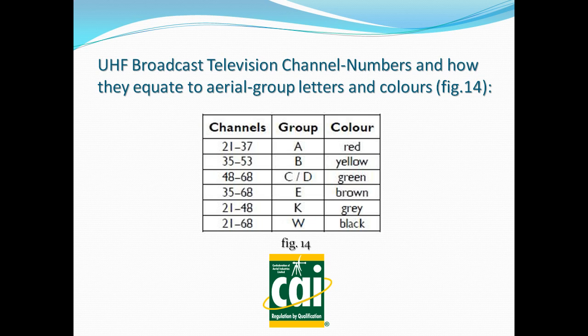In some parts of the country, UHF channels are allocated to transmitters which are spread across both UHF band 4 and 5, and widely for one or two transmitters. That's because of frequency planning measures due to interference from transmitters in neighbouring regions sometimes, and they need to put the DTT in the remaining analog channels if they are being transmitted from a site in question spaced right across UHF band 4 and 5, which is where group W, that's wideband Yagi aerials, come into play.